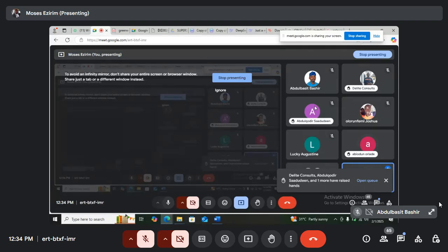But if I have a CNI system where I'm integrating battery, even if my generator is not working and there is no grid, my PV will still be generating because of my battery. My battery will provide all the necessary electrical parameters that the PV needs so it will generate. Does that answer your question?